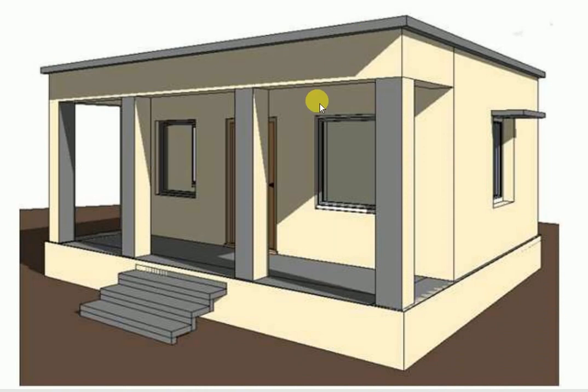Then lintel. It is the element of the building which is provided over the small openings of doors or windows or verandas to transfer the load coming over them onto the wall on which they rest.